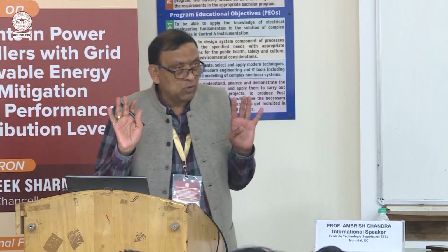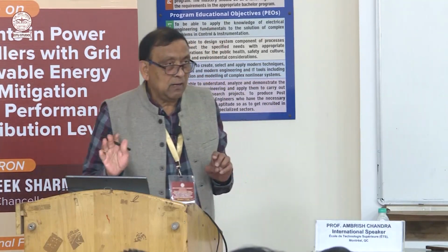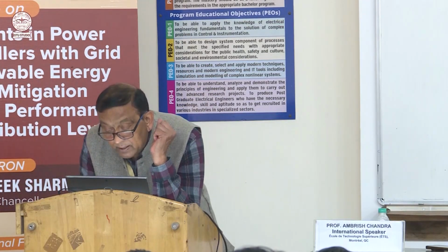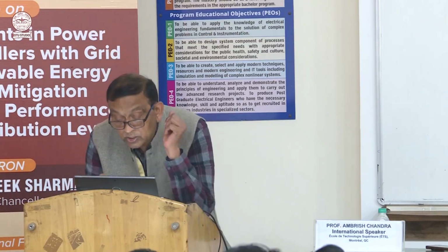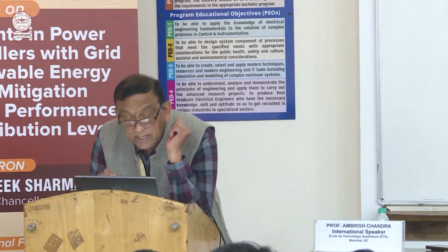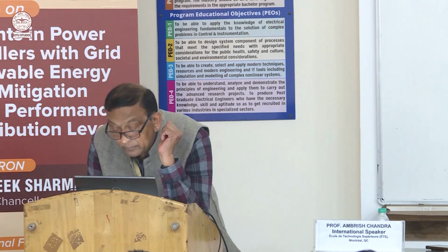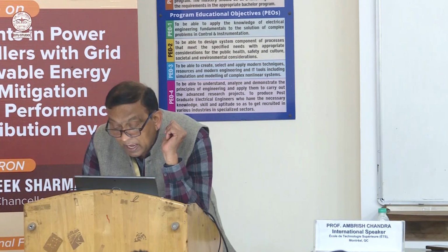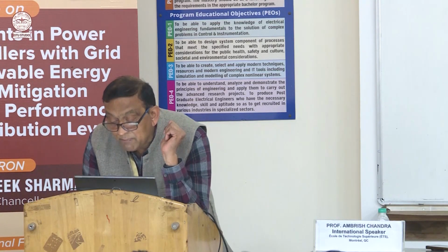The wind farm operator was told, okay, disconnect your wind turbine, disconnect your PV. So what was happening was that these renewable energy sources were supplying only the active power. So if you have a load which needs active power, harmonics, reactive power, everything was coming from the grid.